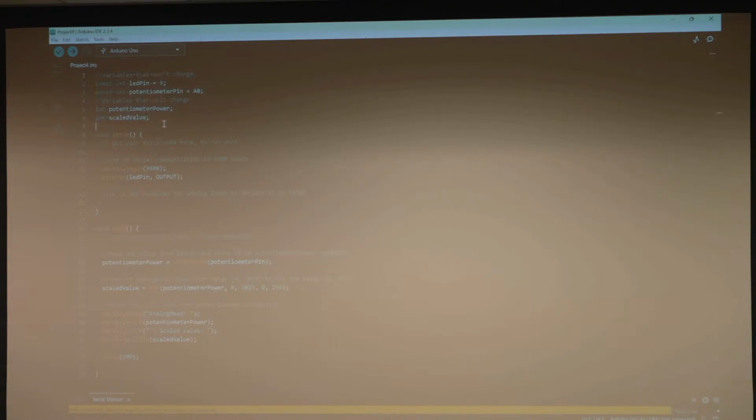At the top of the file we include all the variables we're gonna be using: first the ones that are gonna change, and then we define our constant values. For the constant variables, you're gonna see very commonly that we define the pins we're gonna be using. The pins are basically those little tiny black holes in the Arduino board.